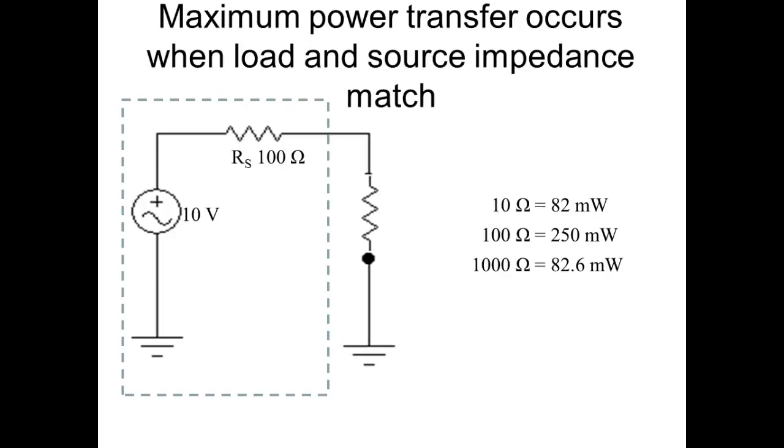And you're right, if the frequency goes up, it depends on how it sets the impedance. Usually it's not that bad, because they combine inductors and capacitors. If the frequency goes up, the opposition of the capacitors goes down, but the opposition of the inductors goes up, and it compensates for that. It's really cool. So in this coax cable, that's what they're doing. They're setting up series inductors and then capacitors.